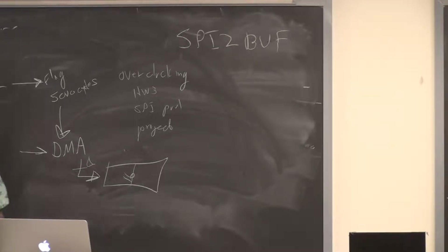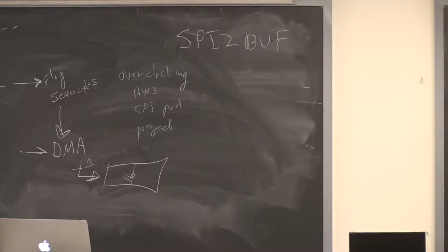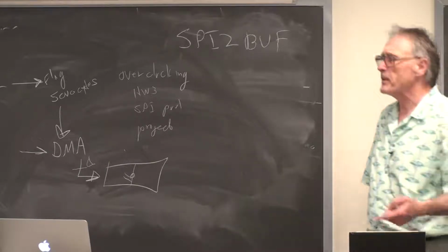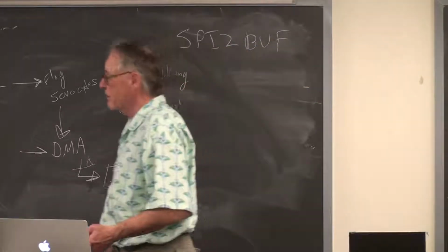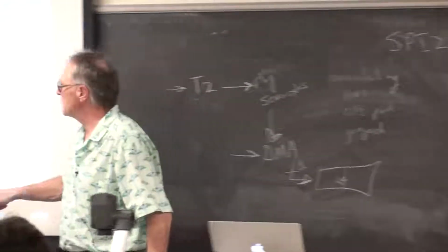As I may have said once before, the only way to figure out whether to reverse the clock phase and phase shift at 90 degrees is to try it with the chip you have. But as long as you stick with Microchip SPI parts, which I try and do, this seems to be the parameter that works.